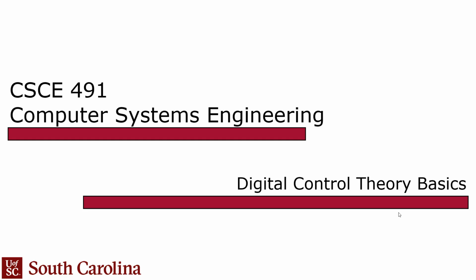Well, it's not even analog. It's worse than that. It's not even a question of it being analog. It's continuous in the sense that if you have an S domain control theory controller, right? You literally cannot implement that in software. It's impossible, right? There's no way to do it. You have to discretize it. So you can either discretize it through the Z transform or through a state space type transform.